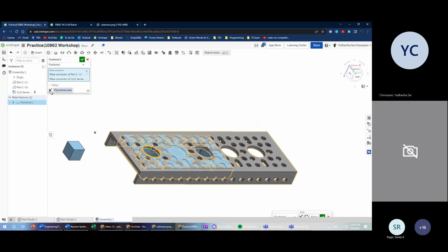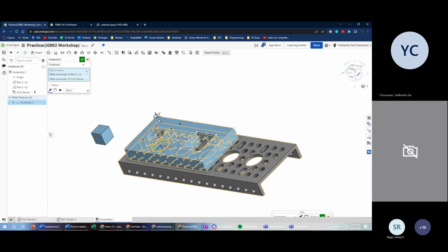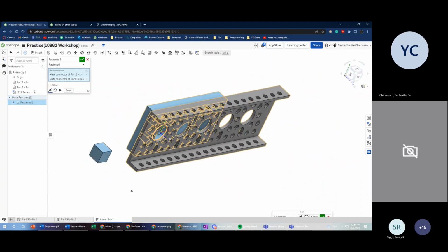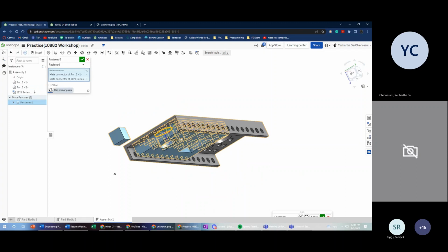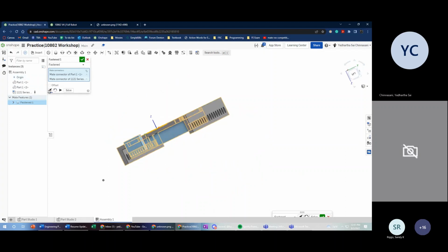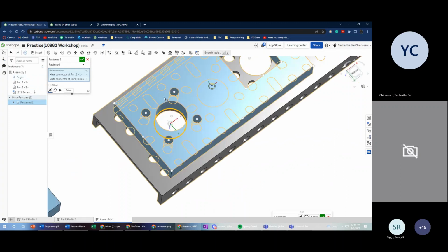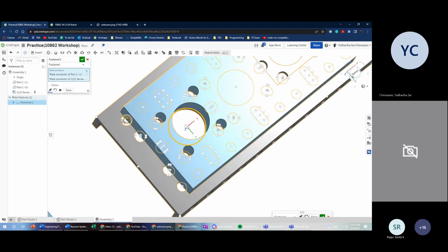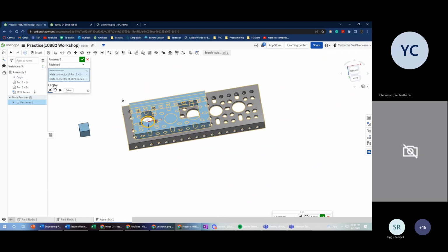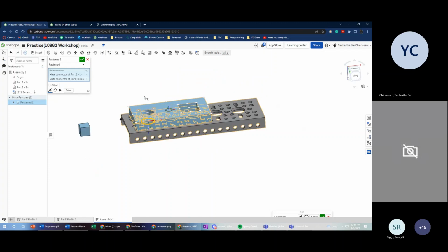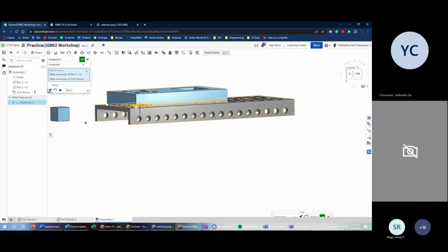There's this symbol in the right here. It says flip primary axis. You click on that, and it will spin it. It'll put it to the other side. So if I click on it again, it'll go through the part. Onshape has a very weird interface with this. I think they're trying to fix this problem. But basically, whenever you see a part going through another part like this, just flip the primary axis,